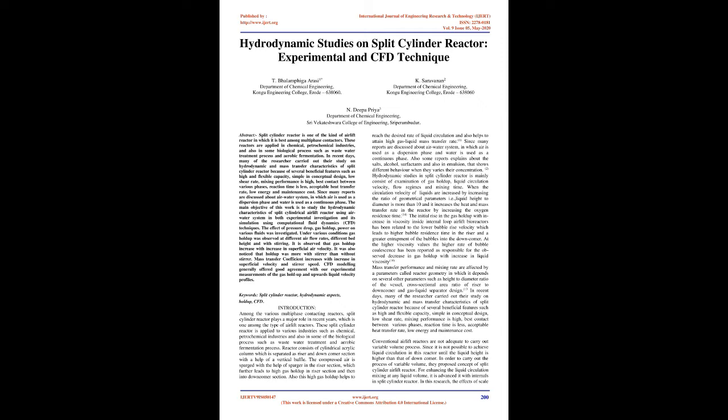It is observed that gas holdup increases with increase in superficial air velocity. It was also noticed that holdup was higher with the stirrer than without the stirrer. Mass transfer coefficient increases with increase in superficial velocity and stirrer speed. CFD modeling generally offered good agreement with our experimental measurements of the gas holdup and upward liquid velocity profiles. Keywords: split-cylinder reactor, hydrodynamic aspects, holdup, CFD.